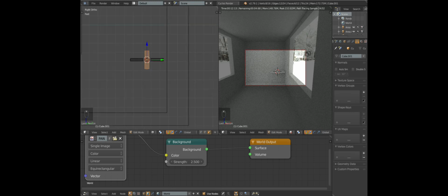Okay, edit, and then you'll notice in the menu, I don't know about you, but I don't think I've ever seen a straight cylindrical lamp like that, because I feel like the light might not work real well. So we're going to add a modifier that most people use a lot to make more curved surfaces. It's called subdivision surface.